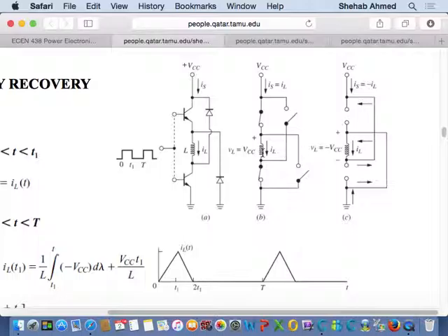I briefly mentioned the current source converter, for example. One of the benefits of the current source converter is that maybe you can use a lower DC voltage to pump current into a higher DC voltage because you're controlling current. So I can take a battery, and out of that battery put a power converter after that that creates current, and in that current's path I put a big hefty inductor. It will maintain that current constant, and it will try to push it to the load. Right. So while doing that, yes, it will create voltages that are higher.